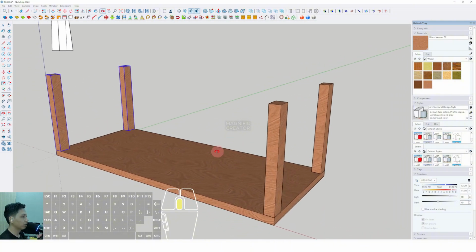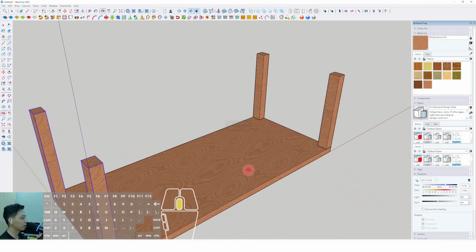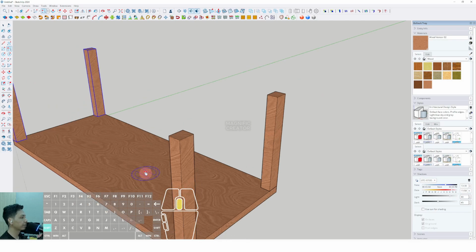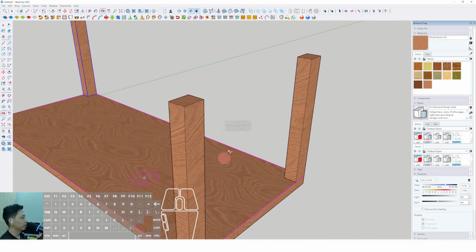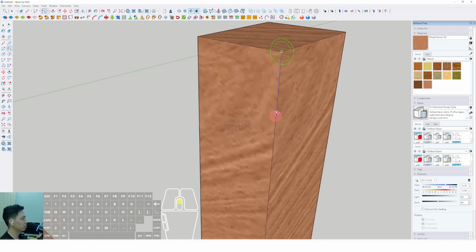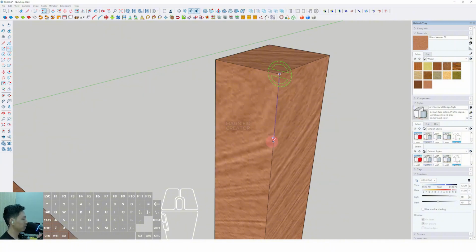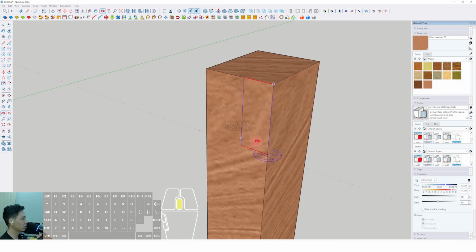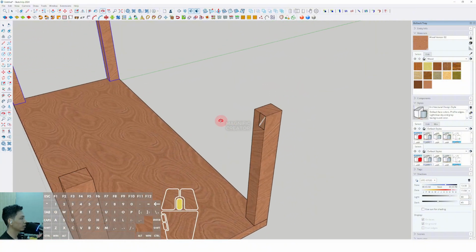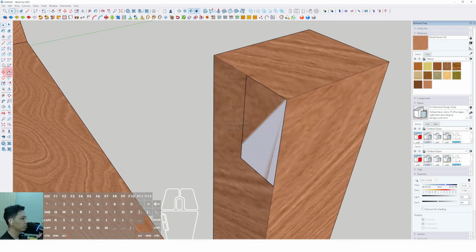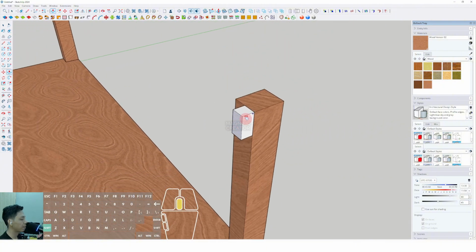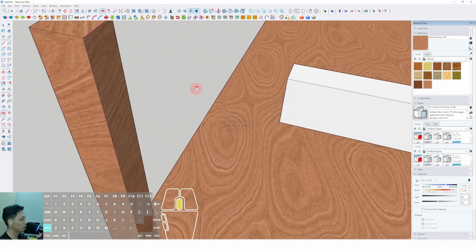Then we can make the horizontal frame. We can make the horizontal frame of this bench using the rotate rectangle again like this. Okay, then we can click this rotate rectangle, place it from this corner and drag to the bottom around 40 millimeters, enter, and set the width of this horizontal frame to around 20 millimeters. Then we can click the surface, click push pull and click this surface again until the extrude appears. Then we can connect the surface to this surface.